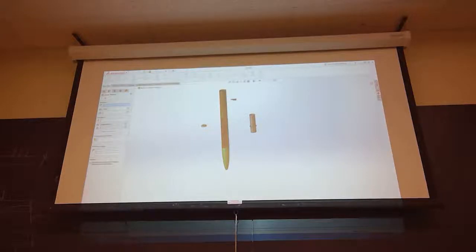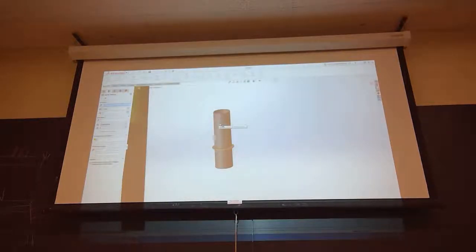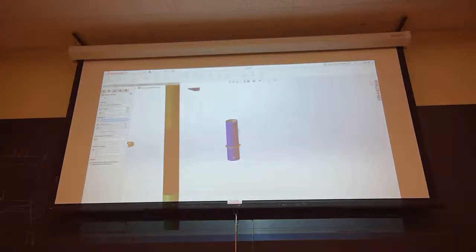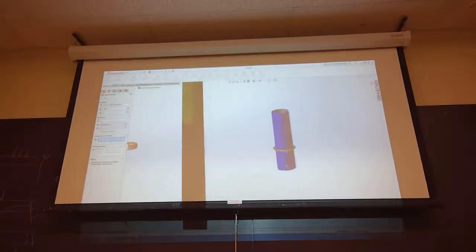The first thing it's going to say is it wants a direction, along what direction or an axis. In this case, we can just hit the outside face, and that'll give it its direction. We want 3 at 5 inches apart. Right now there's nothing in the components to pattern, so you need to select your centering ring.